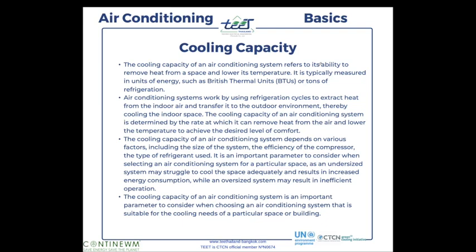It is also an important parameter to consider when selecting an air conditioning system for a particular space, as an undersized system may struggle to cool the space adequately and result in increased energy consumption, while an oversized system may result in inefficient operation.